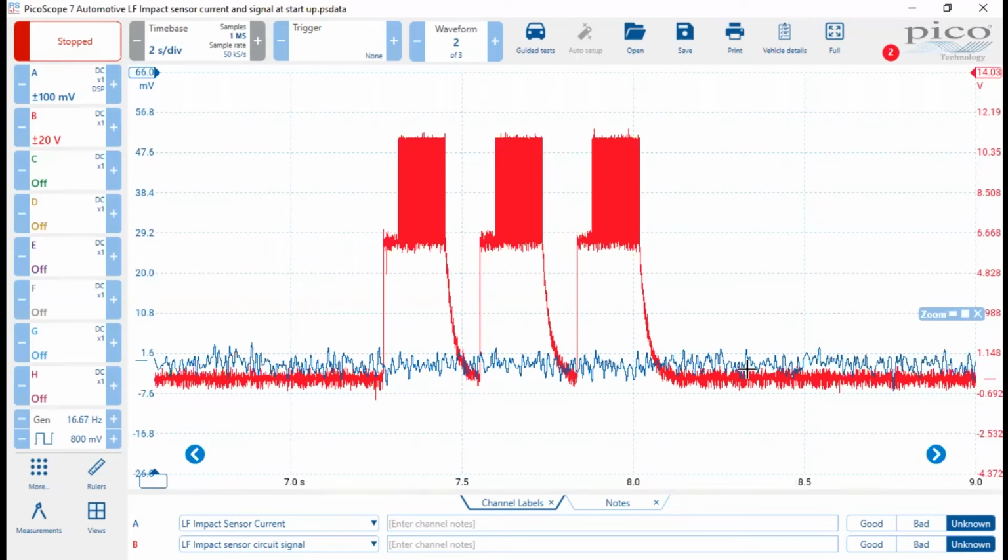And the sensors are brand new and the computer's brand new. So barring everything else, that means either the new module screwed up, or I have an incomplete circuit, but it's not incomplete between my two test points, which only leaves the connectors themselves. So I think what I'm going to do is pull the connectors off and take a look at the pins inside the terminals, which is an unusual failure, but I do believe that's where I've got to go next.